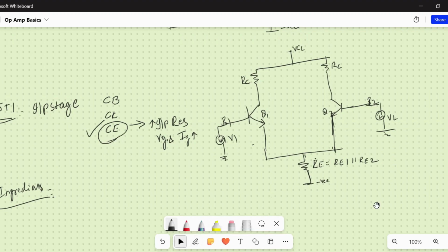So now this is what is called the difference amplifier. For the first section of this particular one, we are going to get the output from the collector side. I call this V1. From the second set, I will get the output, which is called V2. If I take the difference of V1 and V2, I call it V naught. This V1 is with respect to your ground, and V2 is with respect to your ground. And V naught, the difference between V1 and V2, is nothing but your output voltage.